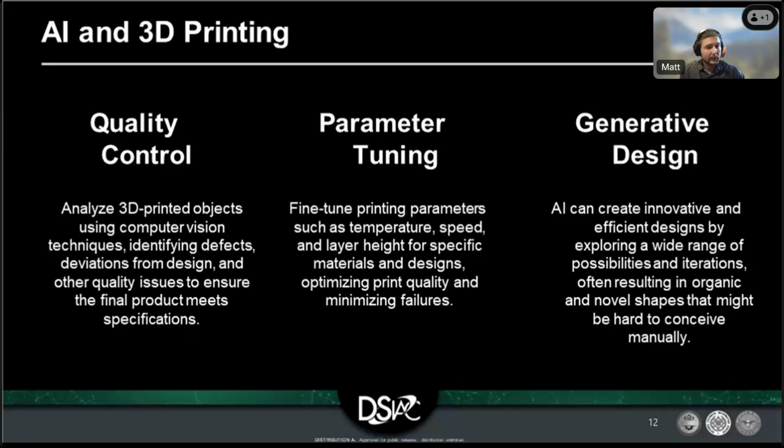So this is more of a forward thinking idea, is that AI is pretty unique. There's a couple CAD softwares out there right now that you can do this. I think it is just called generative design in some of the CAD softwares. But let's just say I have a bracket. The human mind will think in kind of blocks. So I'll probably have an L-shaped bracket, and I'm going to have probably a triangle brace in there, forgetting the word for that. But that's a simple thing. What an AI can do is optimize. So you say, okay, I need it to sustain this amount of force, and it needs to weigh this much.